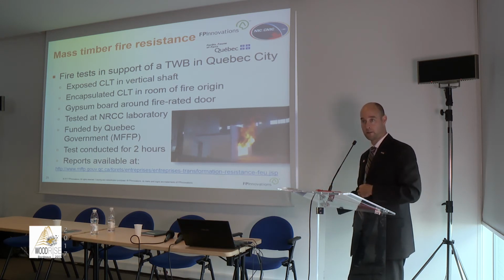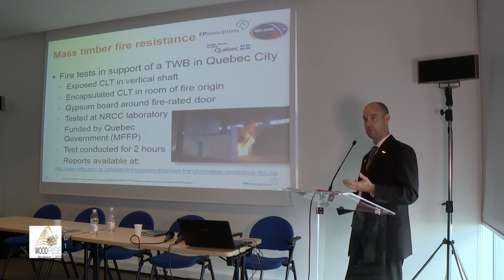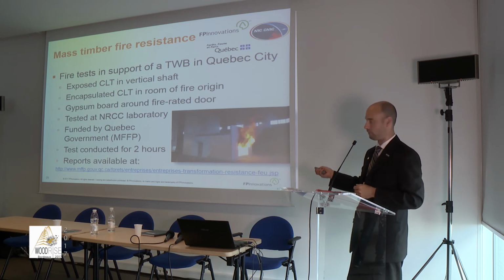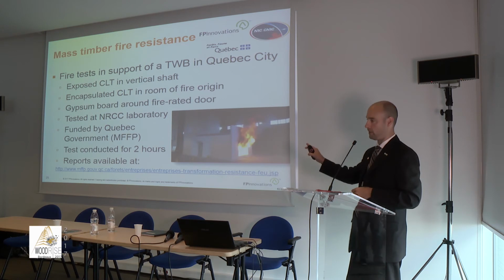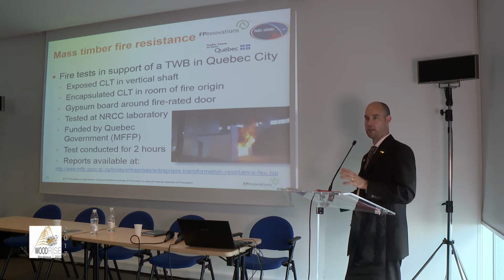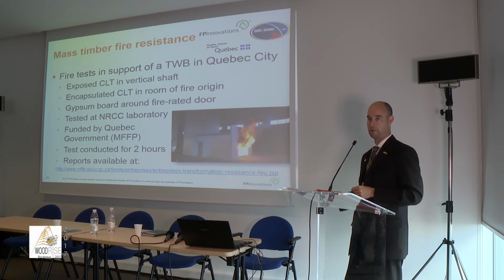The firefighters back home were really against that option, so they were afraid that basically that fire would go through. So we instrumented from the inside all the shaft, and really there was no smoke, no temperature rise at all, even after 2 hours of a real fire occurring in that compartment.